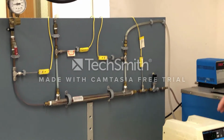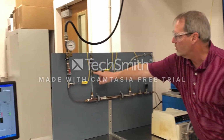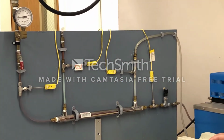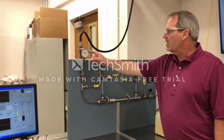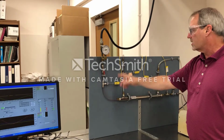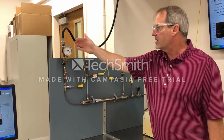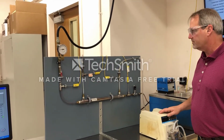On the hot water side, of course, we have our peristaltic pump that's pumping our hot water, and we measure the hot water temperature in and the hot water temperature out. The other thing I should mention is that we keep the inlet pressure of the cold water constant. And so for this geometry and that pressure being constant, we get a constant flow of cold water.